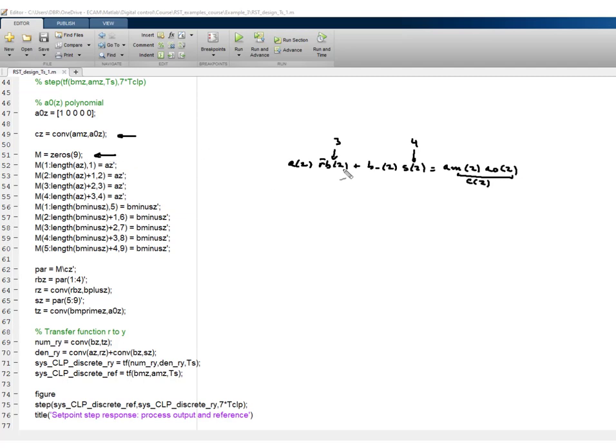So there are 4 parameters in R bar. So we'll have to use A transposed 4 times using the shift operation, and we'll do the same for B⁻ transposed, and we'll have 5 parameters, so we'll have to use it 5 times, each time shifted, and this is going to produce the Sylvester matrix. Then we can compute the parameters.